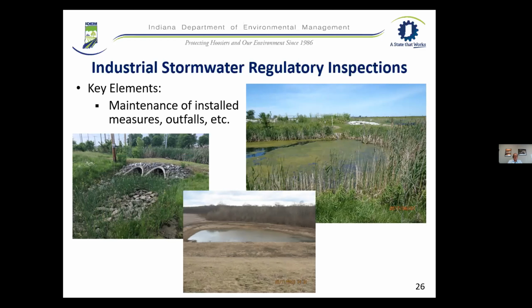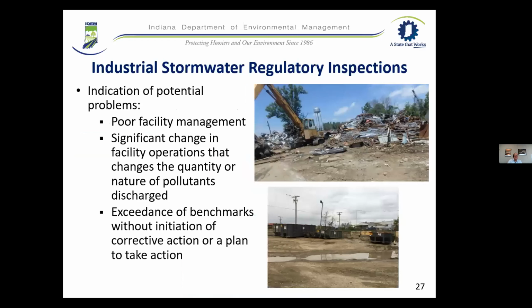Just make sure you have swales or conveyance channels, and make sure those are stable. This is easily picked up on just day-to-day walking the facility, but especially during your quarterly visual monitoring. Just make sure everything's maintained, and that will actually help you as you move into your monitoring program.